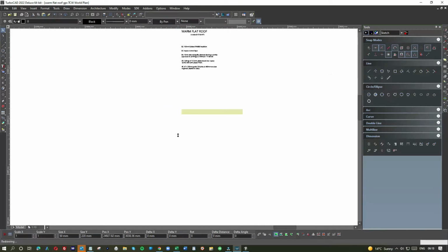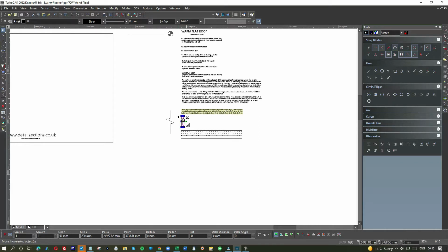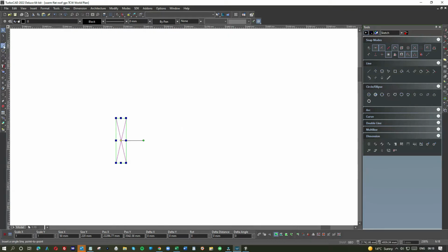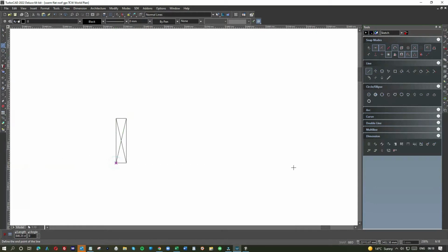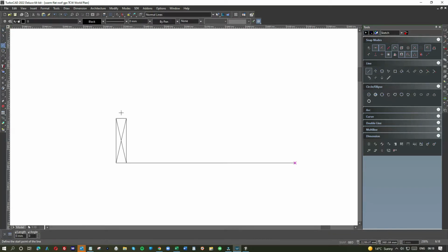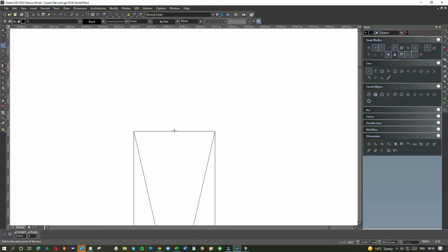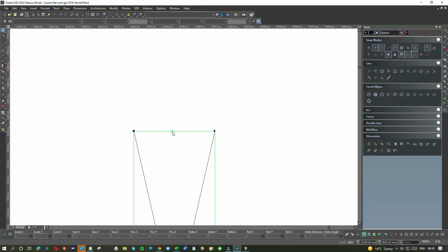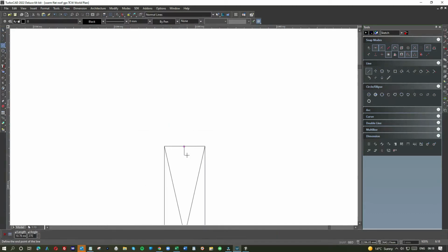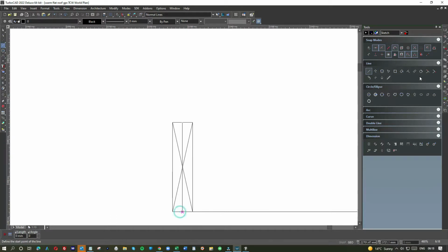This is effectively a ceiling beam or a roof beam, so let's bring it in here. And what we do on a normal basis is we spread these around 400, what we call 400 centers. So one way of doing this now would be to pick up on the center here, and show you an easy way of doing it.